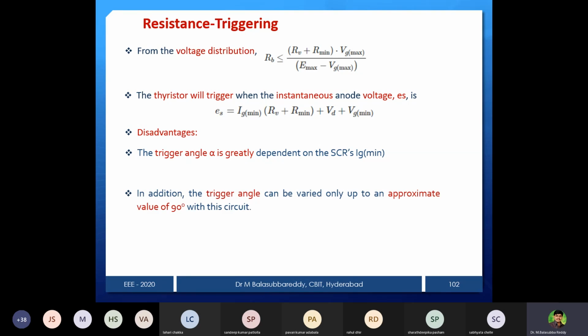That is one drawback. The other drawback is that, because of the supply voltage dependency, the waveform repeats after 90 degrees. Whatever supply magnitude is there from 0 to 90, the same values repeat from 90 to 180 degrees. That is the reason if I keep RV more and more, I don't have higher magnitudes after 90.